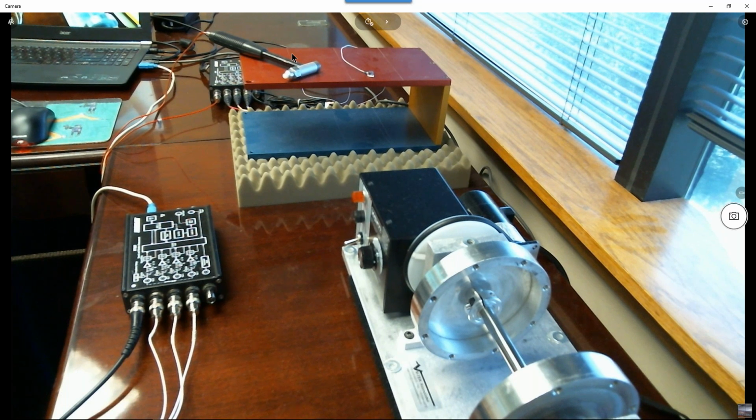And then you can do other things. You can measure an ODS FRF, which we did on the rotor kit, where another way to think of the ODS FRF is the transmissibility multiplied by the spectrum of your reference accelerometer. So you get peaks in your data. You can curve fit ODS FRFs in MEscope. You can get mode shapes.